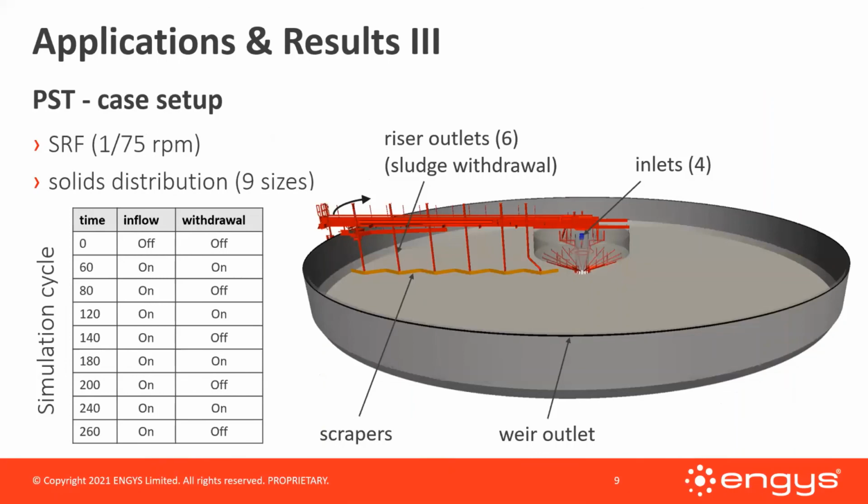The first one is easy. The second one, well, it's our in-house mesher, so it's basically the further development from snappyHexMesh, Helix Hex Mesh. So the mesh consists roughly of 20 million cells, and since it's fully transient, solving for 5 hours of physical time, it actually takes about 8 days on 200 cores. So it's not a cheap computation. And that's also why drift flux is important. Doing this with existing Euler methods may take months.